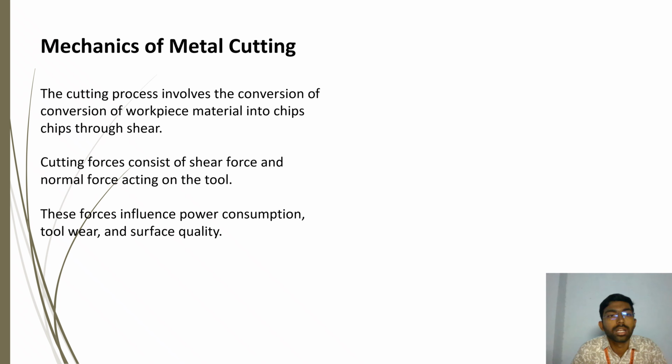Mechanics of metal cutting. The cutting process involves the conversion of workpiece material into chips through shear. Cutting forces consist of shear force and normal force acting on the tool. These forces influence power consumption, tool wear, and surface quality.